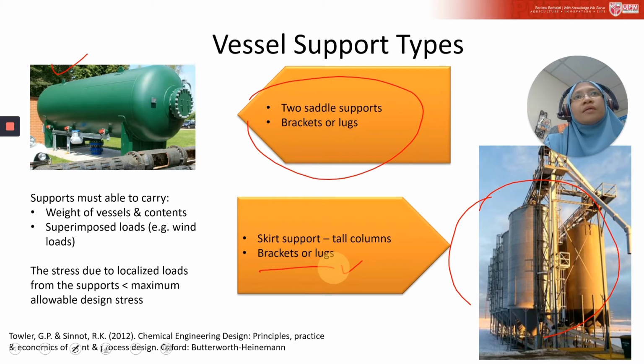You must know that the support must be able to carry the weight of the vessel and its contents, and any superimposed loads that can be caused by, for example, wind loads. The support can also impose localized loads on the vessel wall, and the design must be checked to ensure that the resulting stress concentrations are below the maximum allowable design stress.